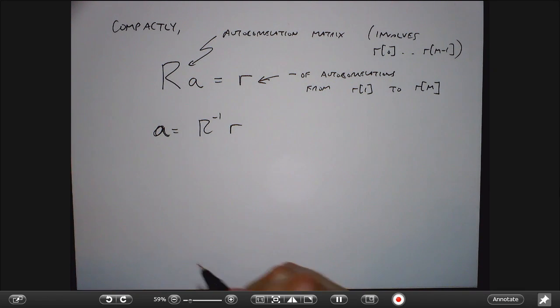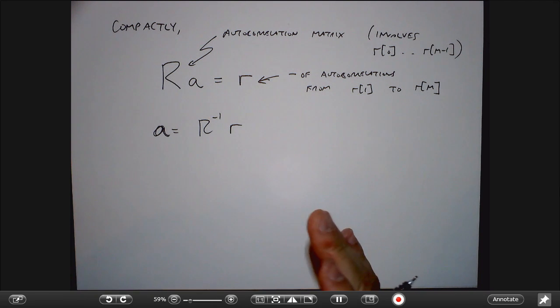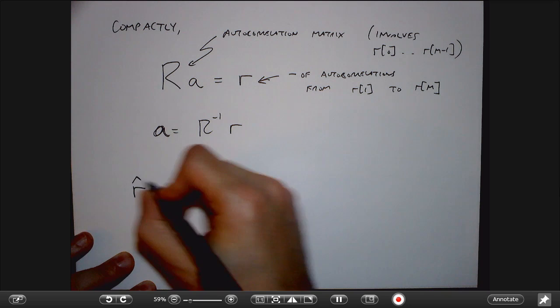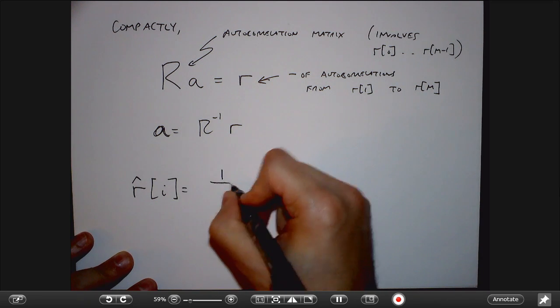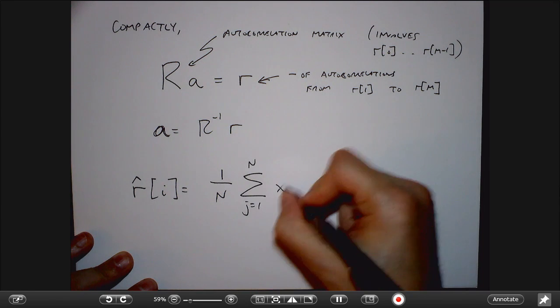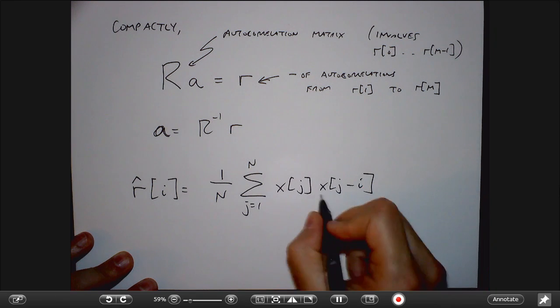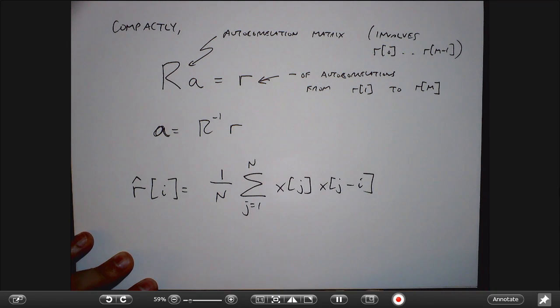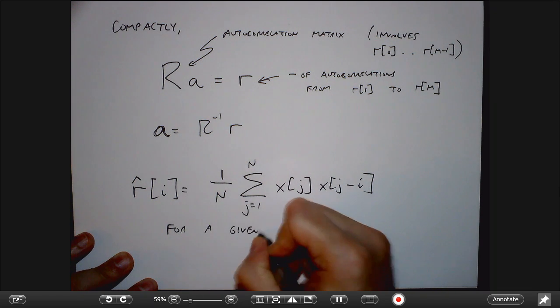Well, just like we would do for a real sequence, suppose I gave you a whole bunch of numbers and said these numbers all come from the same distribution, how would you estimate the mean? Well, you look at the average, right? And in the same way, my estimate of the autocorrelation at a given lag would be to take, over all the data I have, the product of those adjacent samples that have that lag, for a given realization of data.